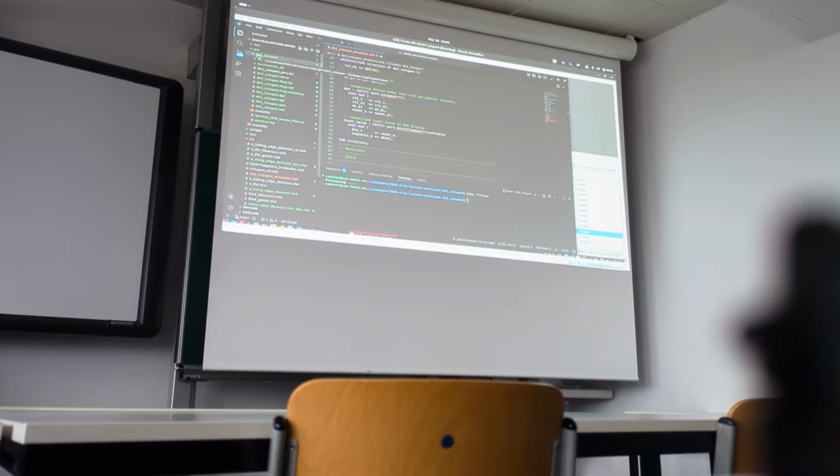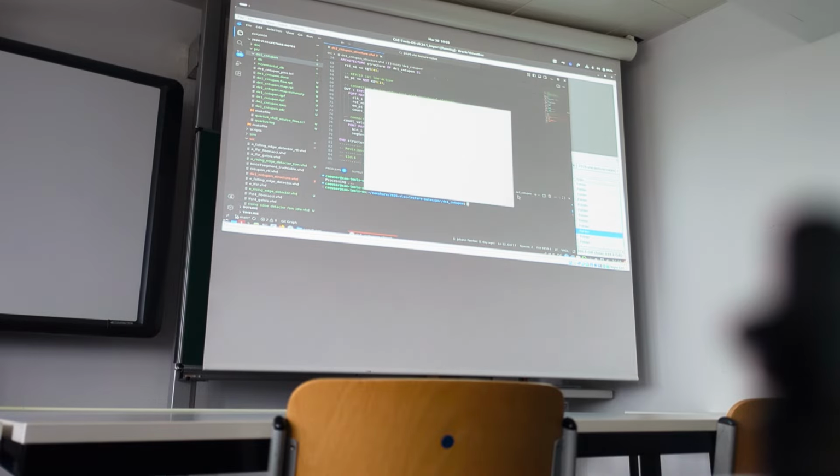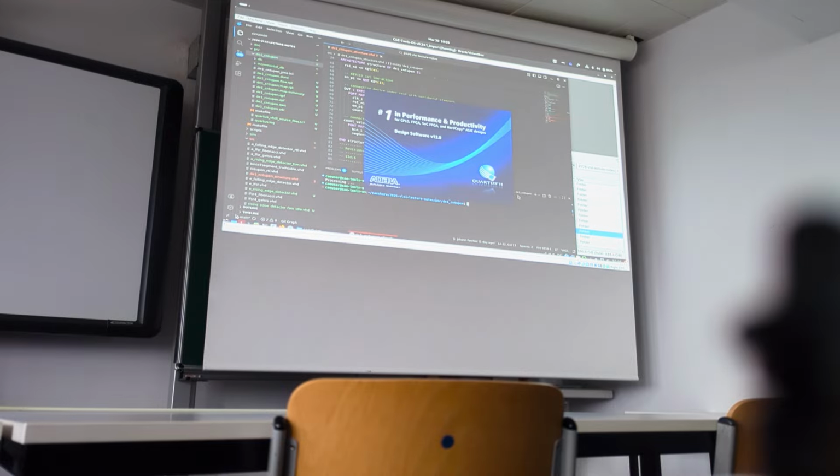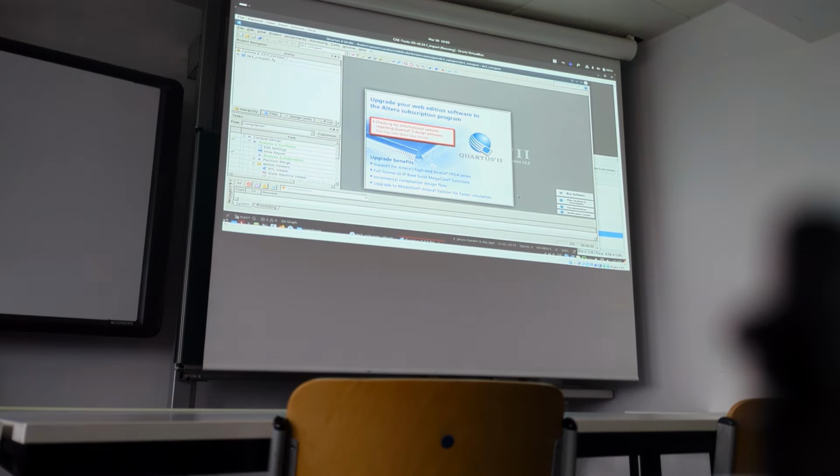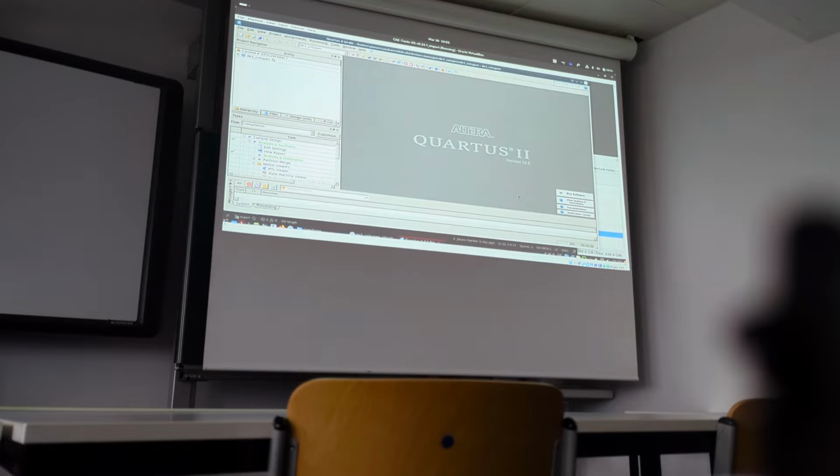The next step is we go to our place and route environment, select that, open a terminal, and just type make RTL view. Then our Quartus backend tool from Intel should start with a graphical user environment.